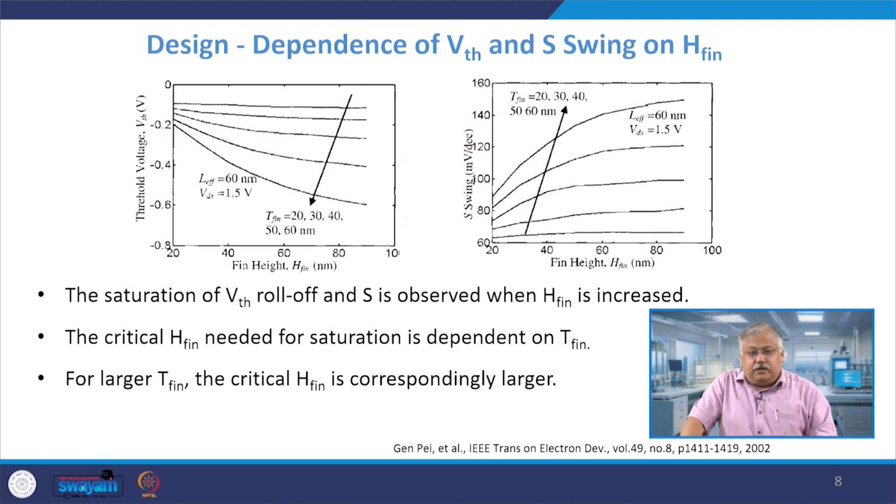So this is where we enter into the region of modeling of the device. We have understood how a FinFET works. It is almost like a bulk device, and the physics behind it is exactly the same. Quantum confinement will come when the width of the fin is very small, lesser than approximately 5 nanometer. Advantages and disadvantages of bulk and SOI we have already discussed.